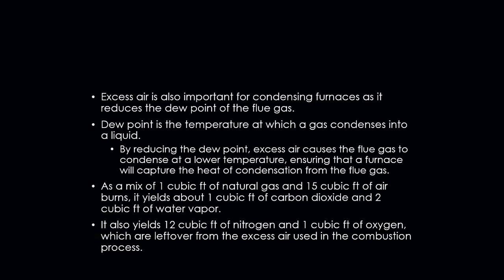Not only does a high-efficiency gas furnace have a primary heat exchanger, it has what's called a secondary heat exchanger. It is that secondary heat exchanger that lowers the flue gas dew point. We are actually using the heat that is escaping out to the flue and using it to heat the space. So we are not only using the heat from the flame entering the primary heat exchanger, but we are also using the heat exiting the primary heat exchanger into the secondary heat exchanger to heat the space as well.